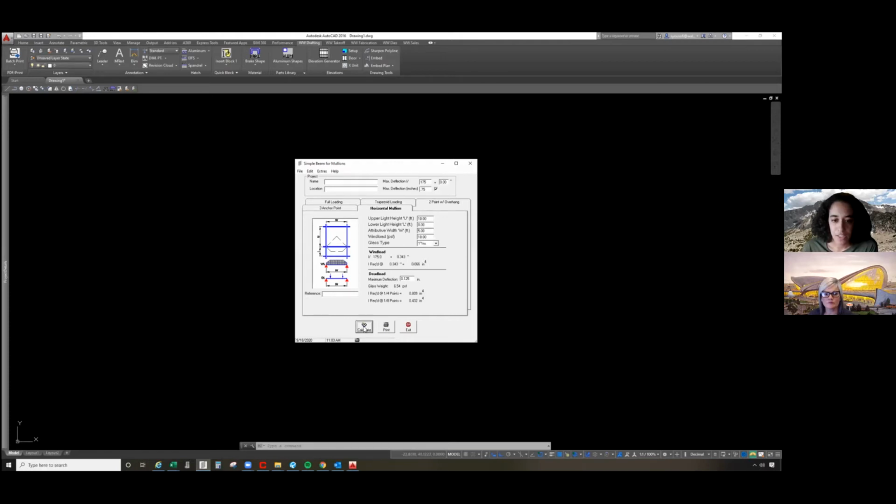Once you hit calculate, it gives you an inertia value required for setting blocks at quarter points, and setting blocks at eighth points. And we compare this value with the member that we're using, and its IXX. So once we analyze that light of glass, we hit print, and it adds it to a queue.